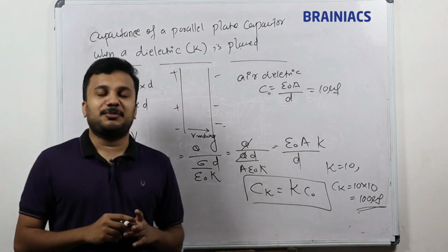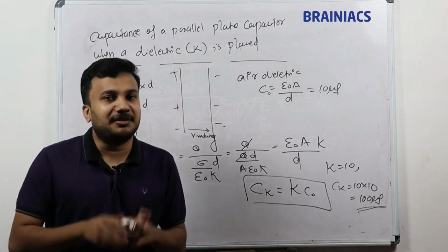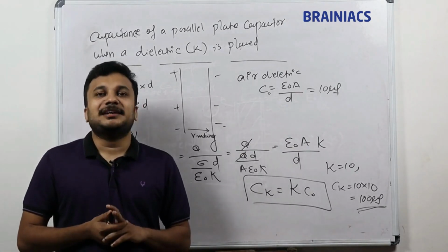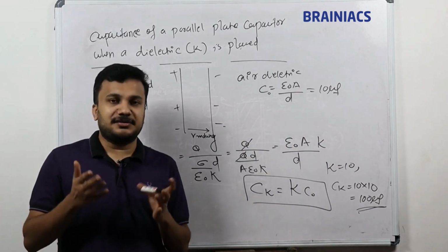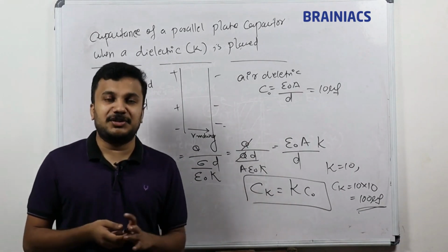You have to connect the polarity in the right way. So if your fan speed is very low, it is recommended to change your capacitor. It is very cheap.